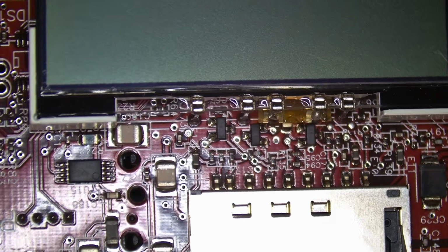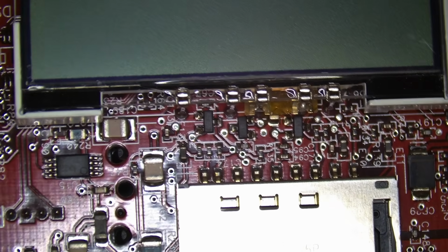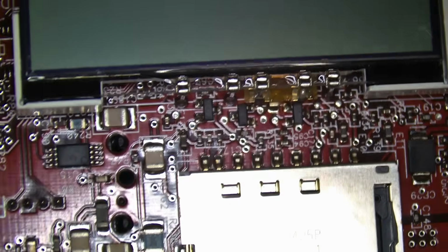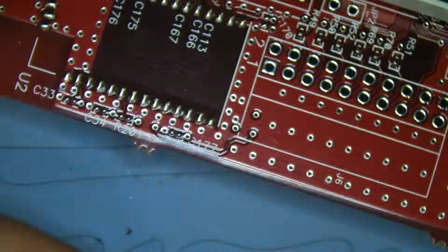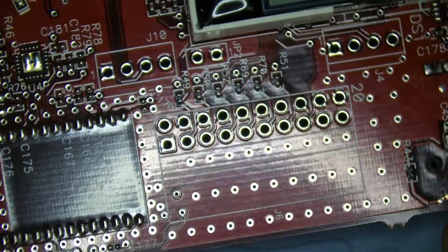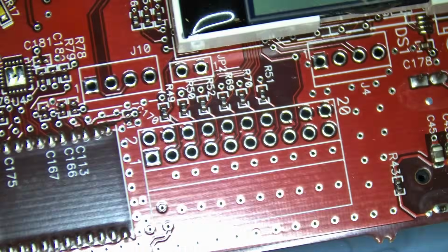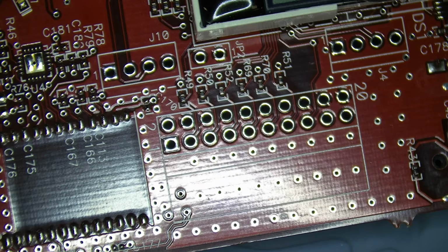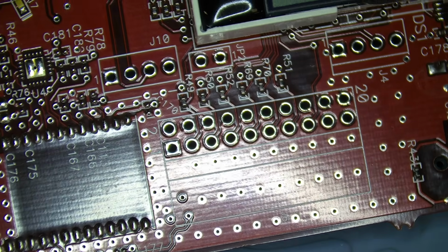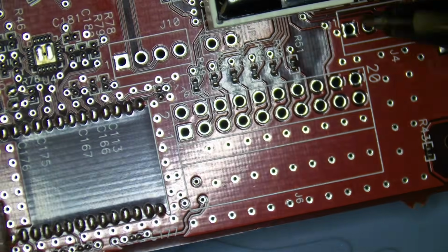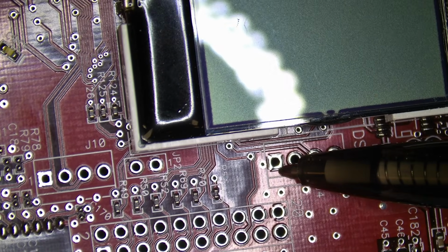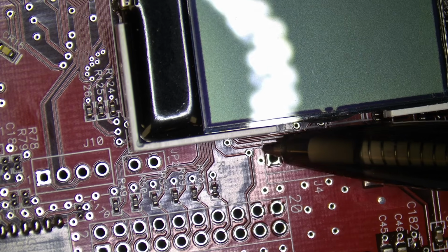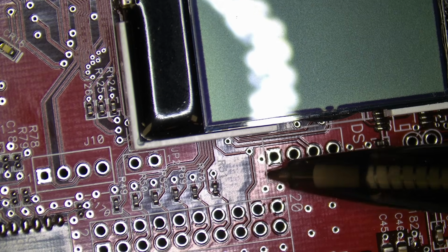Okay, here we go. All right, folks, so this is my fancy dancy microscope. So we can zoom in and I can show you those headers that we talked about earlier. And right here is the edge of my display. And one of these really looks like UART and the other one, maybe not. The square pin that I mentioned, see right here how it's connected to the solder mask and the edge.